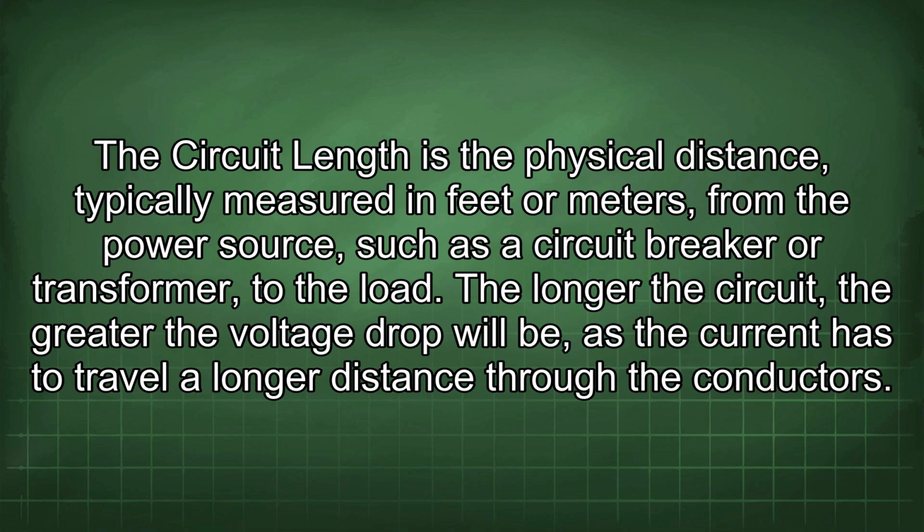The circuit length is the physical distance, typically measured in feet or meters, from the power source, such as the circuit breaker or transformer, to the load. The longer the circuit, the greater the voltage drop will be, as the current has to travel a longer distance